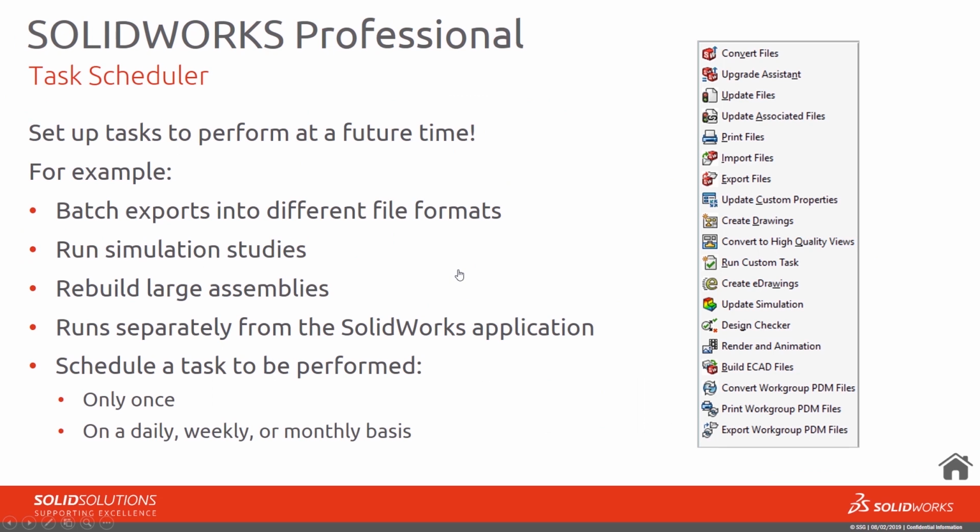We've then got Task Scheduler. Now this is a really cool tool that basically allows us to do things like batch conversions. So if we wanted to, for example, take a technical drawing and we wanted to save them into both a DXF and a PDF format, instead of doing that manually for each drawing, we can create all of our technical drawings, and then maybe over lunchtime or overnight, we can say to SOLIDWORKS, look, take all those technical drawings and save them out into DXF and PDF files for me.